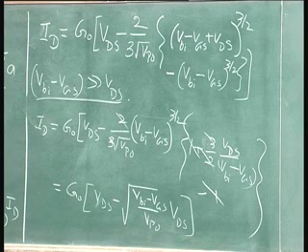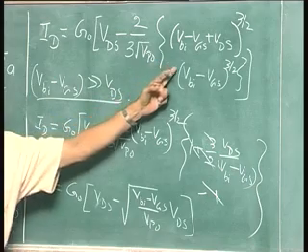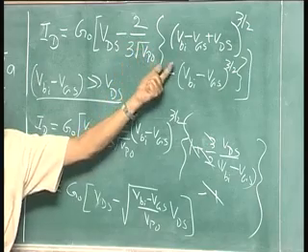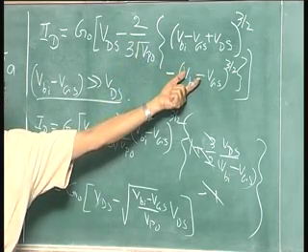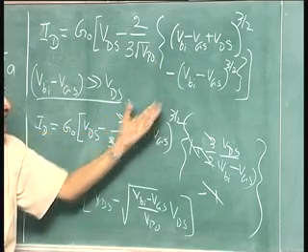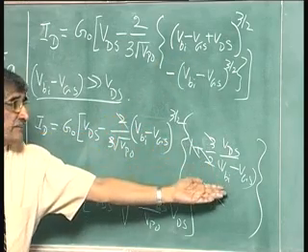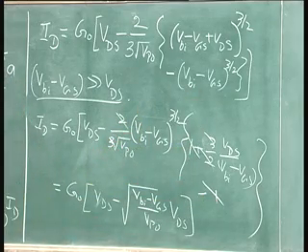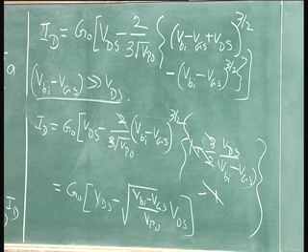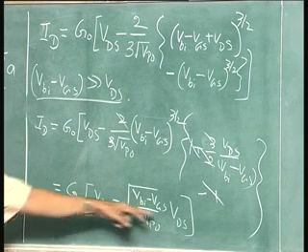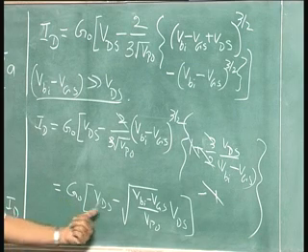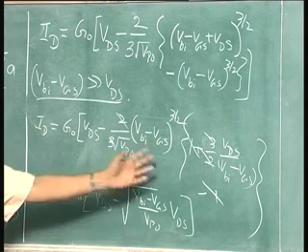So, what we have done is just expanded this particular term, binomial expansion, pulling this (V_bi minus V_gs) out, you get 1 plus V_ds divided by (V_bi minus V_gs) to the power 3 by 2. That we write as 1 plus 3 by 2 V_ds by that. So, that second term we have pulled out, and the minus 1 makes these cancel out. So, it is very simple. Now, what we have written there is we have pulled out this V_ds from inside the bracket, you get it as G naught into 1 minus the square root of (V_bi minus V_gs) by V_p0, into the whole thing into V_ds.